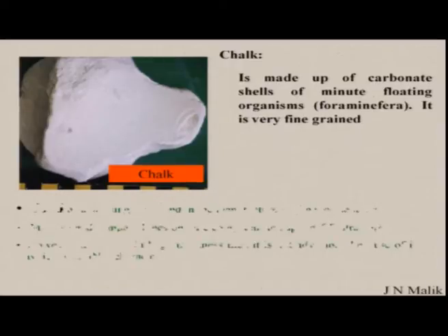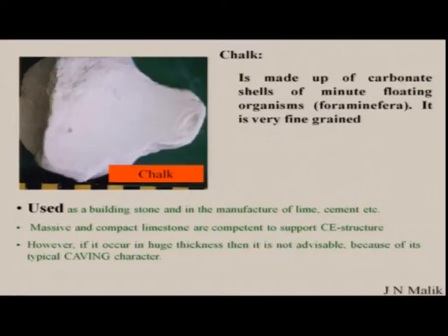A very fine grain rock, used as a building stone and in the manufacturing of lime and cement. They are massive and compact in nature, so they are competent to support structures. However, if it occurs in huge thickness, then it is not advisable, because they typically have caving characteristics.